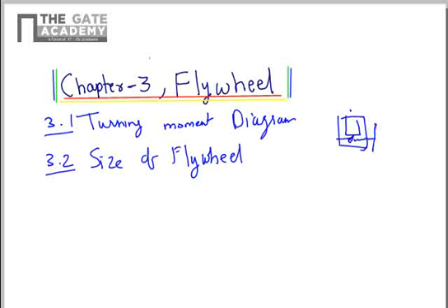At the exit of the engine, you must have seen a big wheel of solid mass, which is not having any function related to the transmission of the forces or the working of the engine, but it is just attached to a shaft, and then this is coupled to the output, whatever it may be, a generator or a vehicle. So this intermediate thing is a flywheel, which is a solid mass